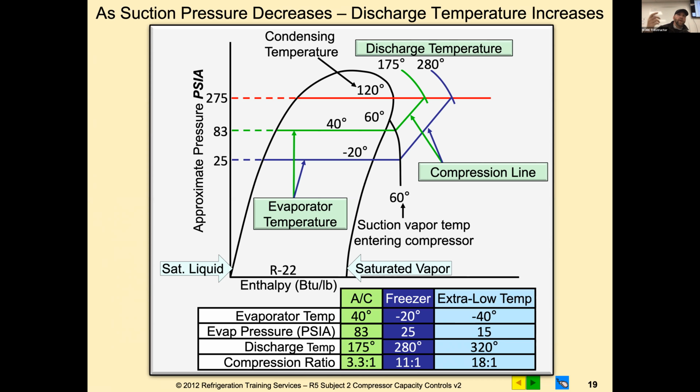If you understand when it's supposed to do what it's supposed to do, it'll help you understand why we're still gaining heat and why we're not cooling our compressor. If it doesn't have a lot of heat absorption capacity, because we don't have the volume of refrigerant we need, and refrigerant will only absorb so much heat per pound, that's what enthalpy is. If there's only so much vapor in there, we can only absorb so much. That means the heat continues to remain at the compressor, and it adds up and adds up, so you're not adequately absorbing for the size and tonnage you're dealing with. That's what's going on. That's why it continues to overheat.